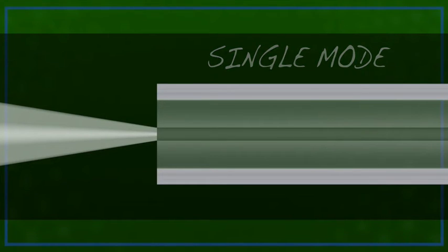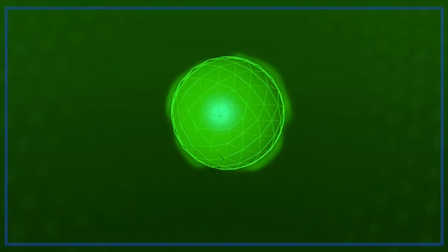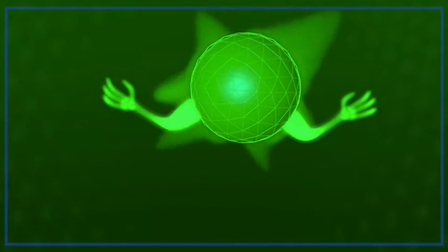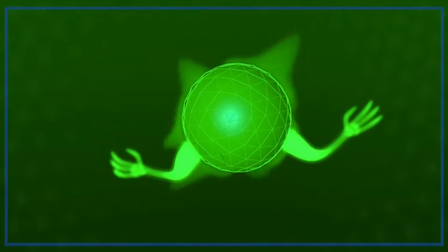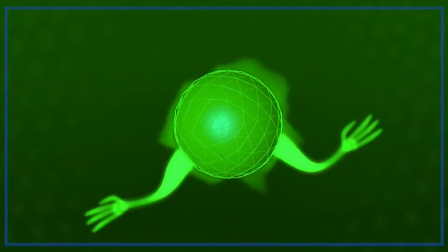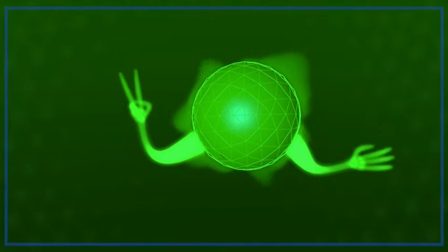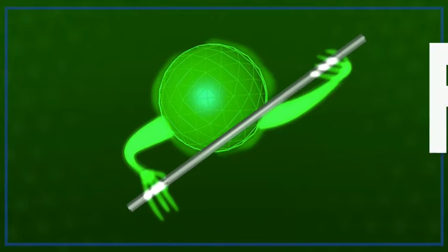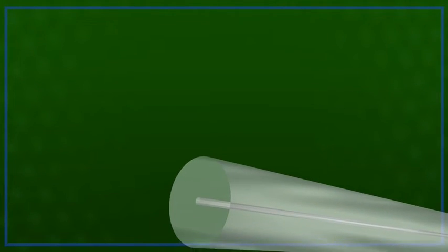Depending on the size of the glass rod, the refractive index, and the wavelength, the core can be both single or multimoded. We strive for single mode. So, we generate certain wavelengths and use glass rods with diameters in the micrometers, less than 2 human hairs in diameter, small enough to be greatly flexible and resilient. Fibers usually have one core and one cladding along with a protective coating. Most are made of quartz glass because of its purity.